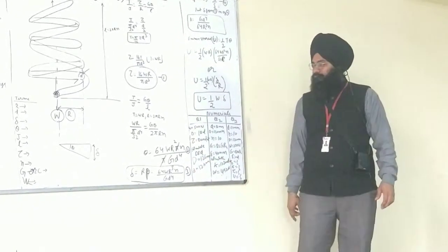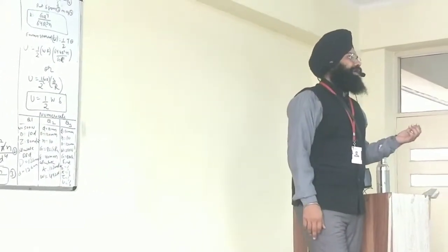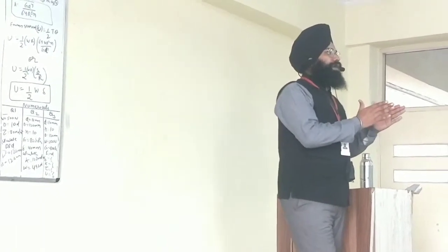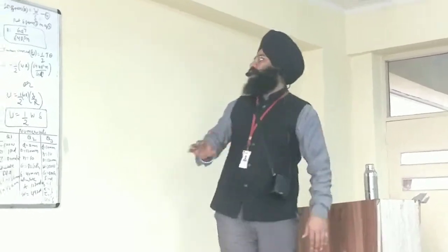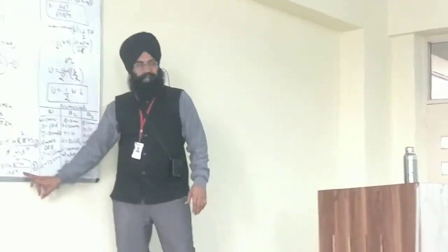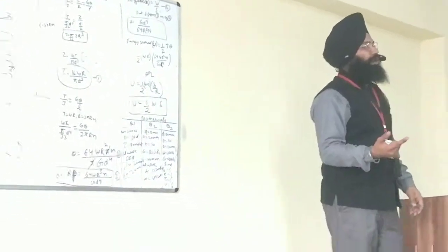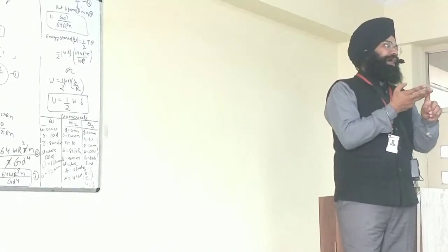We know that to calculate deflection, deflection will be equal to R into theta. R is the radius of the spring. And you have calculated theta, so deflection can also be calculated in this relationship. So now, further we come to the next relationship. Now we have calculated the shear stress, deflection and twist.